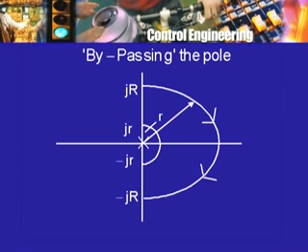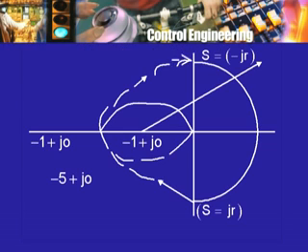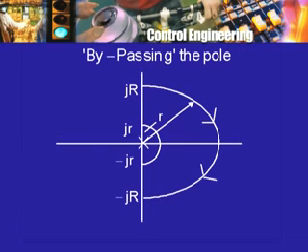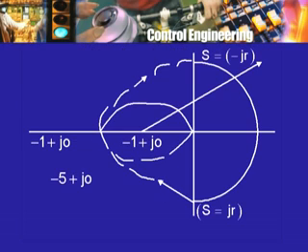So, it is going to change in the opposite sense. So, corresponding to this point where the phase is minus pi by 2, the phase of k by s g h will be plus pi by 2, and that is indeed correct. I am here. Corresponding to the other point j r, where the phase is plus pi by 2, k by s g h will have a phase of minus pi by 2, and that is correct.